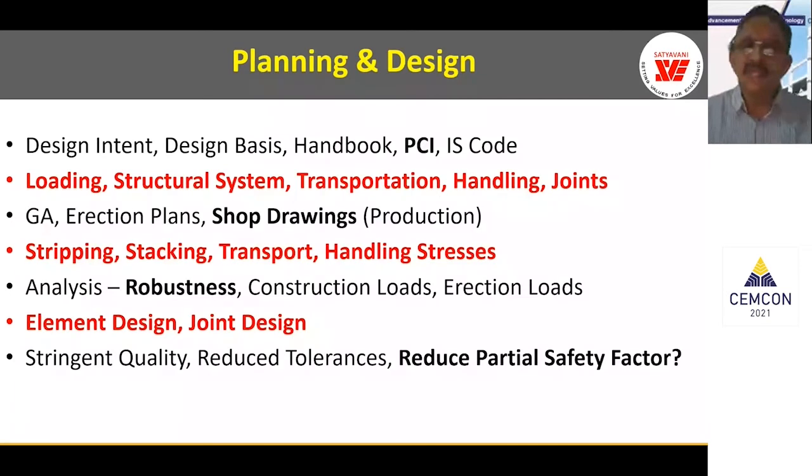Loading, structural systems, transportation, handling, and joints are to be kept in mind while drafting the design intent and doing the planning. That means right from the initial framing plans that we prepare, we have to consider the type of construction that we are going to propose so that we will be able to deliver in the time available. The general arrangement drawings, erection plans, and shop drawings are to be prepared by the consultant and utilized in production of the precast elements. Stripping, stacking, transport, and handling stresses are to be considered in the design of these elements, and these are all readily available in the PCI code.